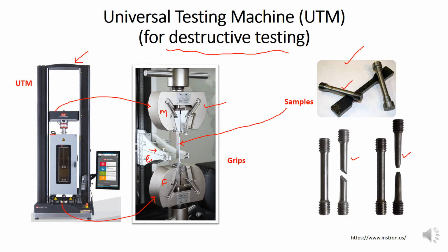And the fatigue testing, the creep testing, tension, compression, shear, bending, all the tests can be performed on a universal testing machine at room temperature as well as higher temperature and low temperature. For low temperature you use a liquid nitrogen supply in this environmental chamber, and that maintains the low temperature.